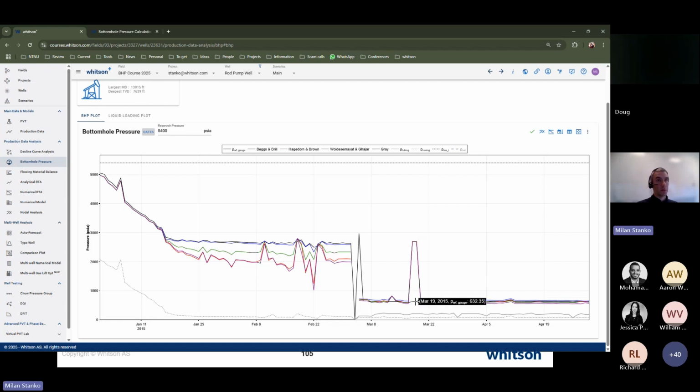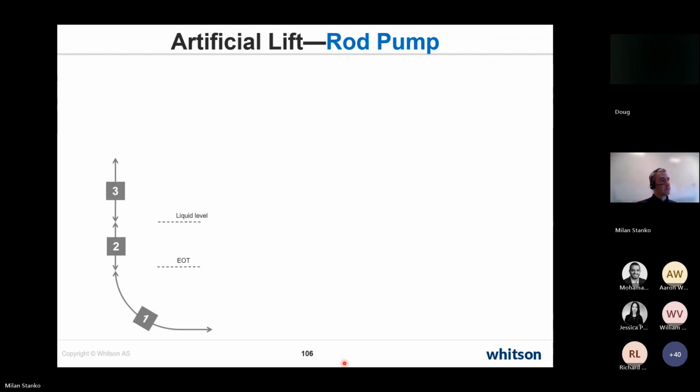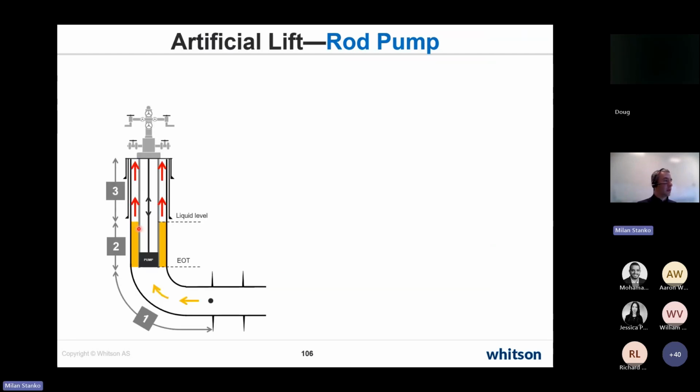The value for some reason was defaulted to 0, and then it is making like I have a very big column of liquid, going all the way from the top. If I look at my slide, this liquid level is not 5,000, not 5,500 like we saw before, but it's actually some value up there. And because of that, the pressure will be much, much higher at the bottom.